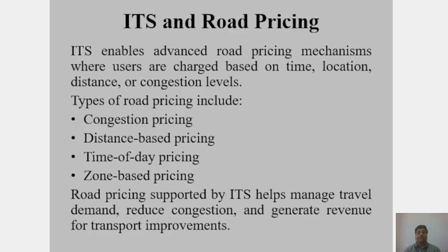In order to relieve that congestion and have free flow of traffic at that location, ITS has been included with road pricing, where the road users pay a specific tax or amount that can be used for proper ITS implementation at that junction or urban arterial.